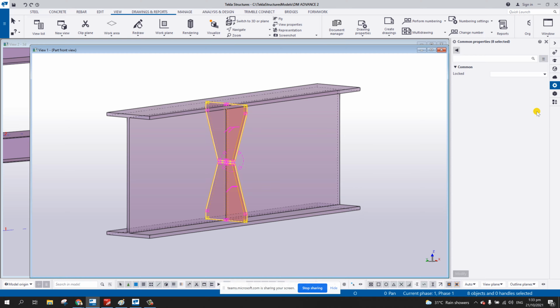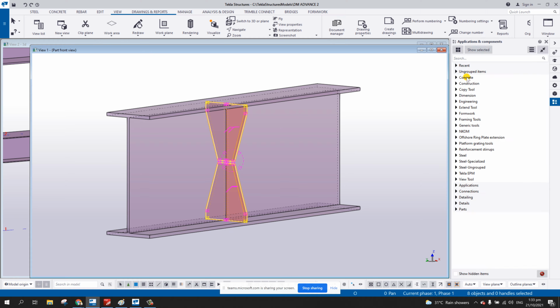After you select this one, you need to go to the right hand side and define the custom component. I added only one weld for the meantime. You can add more later if you like. For this example, I just use one weld each, just to attach this one to the beam.